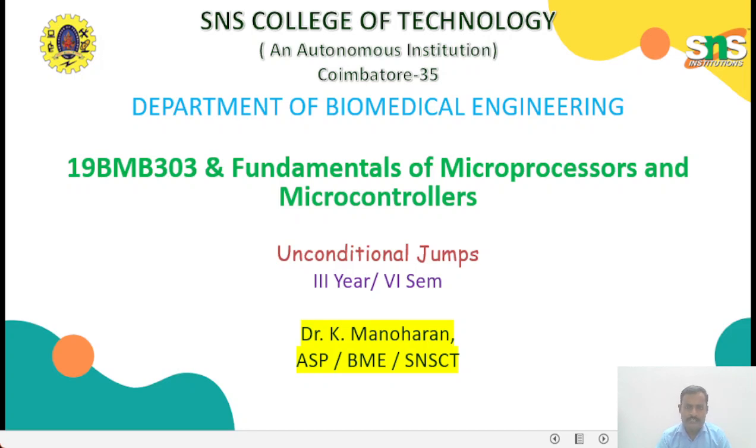So today in class we are going to discuss unconditional jumps. Jump initiation can be classified into two types: one is an unconditional jump and another one is a conditional jump. A conditional jump checks the condition; if the condition is satisfied, it takes the jump. If it is an unconditional jump, then no condition will be checked. Once we have an unconditional jump, it directly takes the branch.